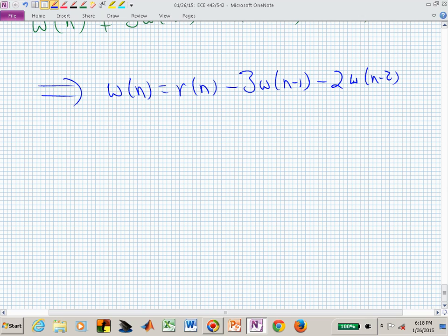And we want to now create an all delay block diagram that will essentially solve this linear difference equation. If somebody injected into this block diagram an expression for R of n and established the W's at the appropriate initial conditions, maybe it's initially relaxed, so there's no initial conditions, but R is something non-zero, then this block diagram will crunch through the values and be generating numerical values for W of n.